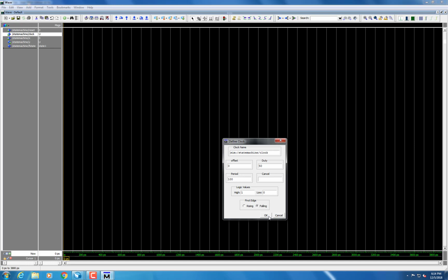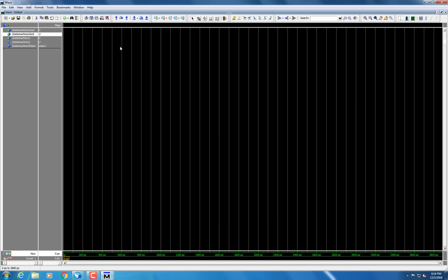After this, set your inputs for what you want the simulation to be. This can be done by right-clicking the inputs and forcing them to high or low in the Force section. This can be a little tedious as you have to do it slowly with your inputs that are irregular.